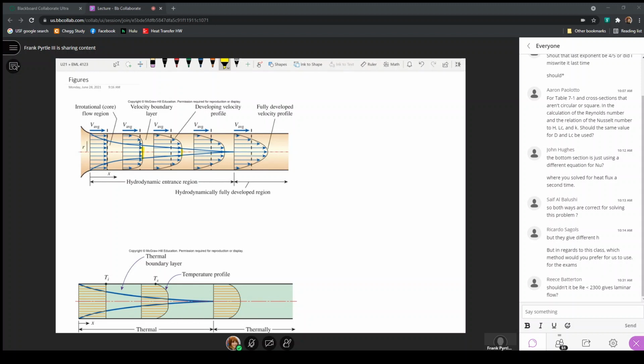It's still uniform there. It's increasing in velocity, but it's still uniform until that boundary layer grows together. And then we have a single point here where the velocity is maximum along the center line and 0 still at the end. At each one of these places here, I'm going to just draw a green X.